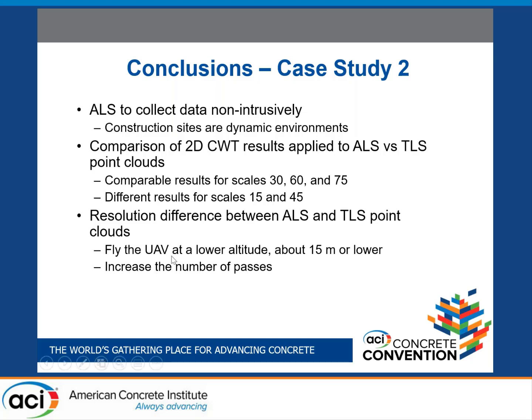Again, one of the things that can be done is flying the drone at a lower altitude, and increasing the number of passes could also help to increase the resolution of the point cloud that you obtain.